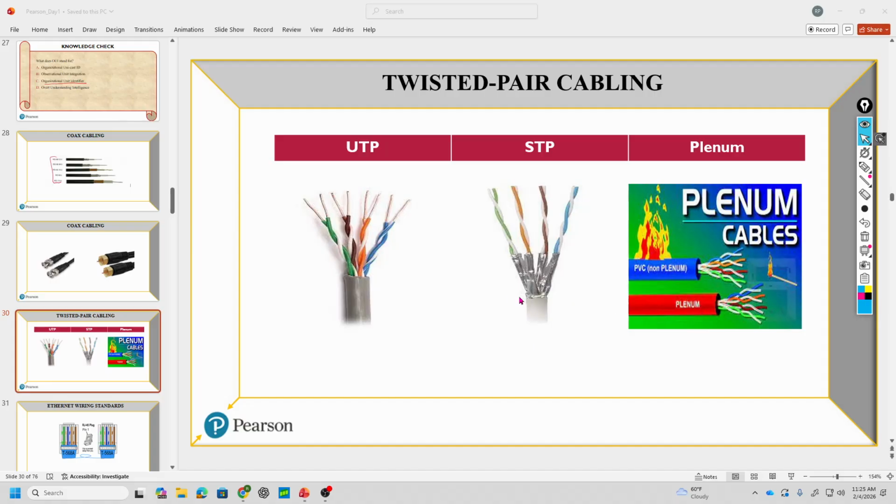It is a rubberized type of coating. If you've ever worked with anything like heat shrink, when you put the flame to it, it just kind of shrivels and melts. It does not burn, it does not catch fire. And so this is used in high heat areas where, like around the HVAC systems and anywhere that's super high heat that could possibly ignite, you use plenum. But it is very expensive, and we only use it if we have to.